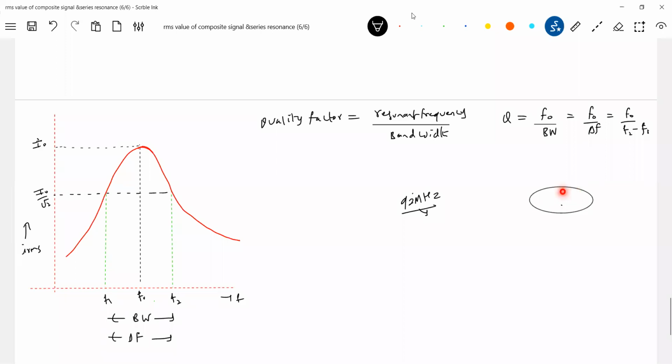Or let's put 0.5 megahertz. In this 0.5 megahertz, I'll put all the information. What is information? What all I speak, the music, everything generated in the FM station. So that everything will be accommodated in this particular range. So now what is the bandwidth? 92.5. Where the station will be available for us will be 91.5 megahertz. So all this will become the bandwidth here.